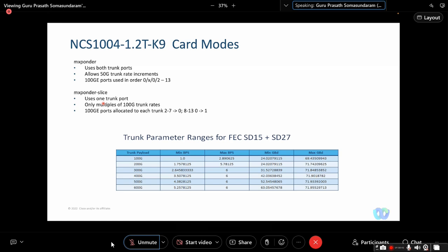As called out before, the baud rates are entirely configurable for each rate, based on your line system capacity. In this solution, we are using a fixed 64 channel, 75 gigahertz spacing, so all the baud rates configured are 63 gigabaud or 64 gigabaud to fit in that.